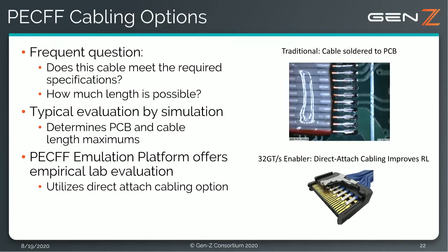So how do we pick our cable? How do we know that it's going to work in our Gen-Z system? Does it meet any specifications? How long can I make it? Those are all excellent questions. They're popular questions. The number one answer here is this is evaluated by simulation. Using the tools available to the industry, one can determine what's the maximum length allowable for your cable and/or PCB, or a combination of both.